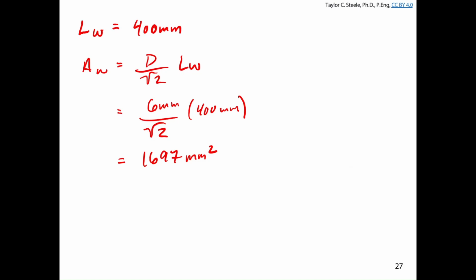Question? Calculation. We'll calculate the strength of the weld on its own. We have 0.67 phi w Aw Xu. Do we need to multiply it by the factor 1 plus sine of theta to the power of 1.5 here? It's 1, right? So technically, sure, we could include it, but we know it's in direct shear, and S16 gives us the strength of welds in direct shear without the factor.